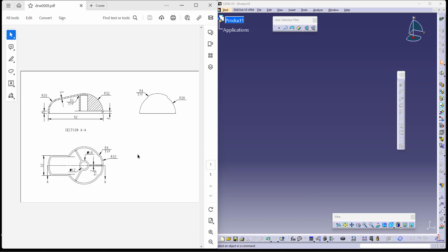So firstly, with understanding our views, there are three views. This is a third angle projection, but instead of projecting the front, the right and the top, the drawing actually shows front, right and the bottom, because the features you are seeing here describe the bottom side of your body. On the upper side we only have the conic or arc shape, so we prefer not to take that view and rather take the bottom view for better understanding of the actual model.